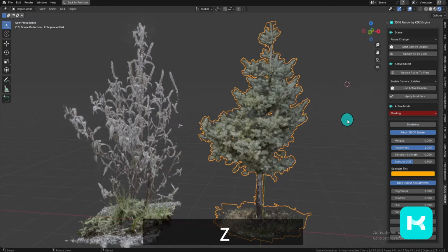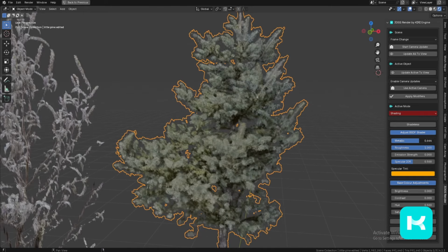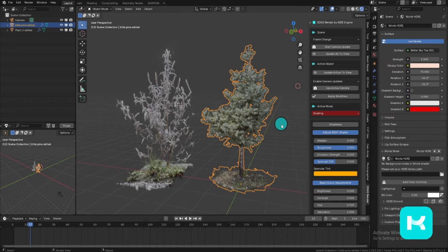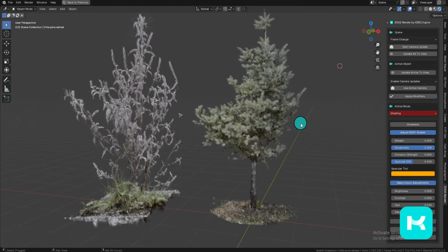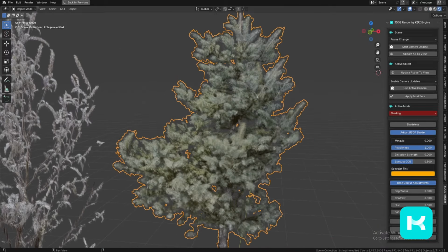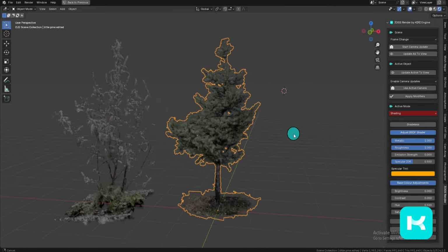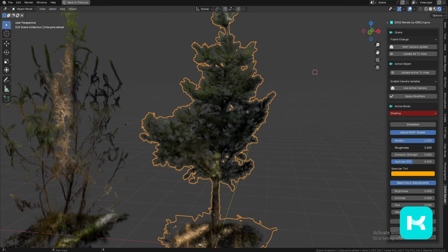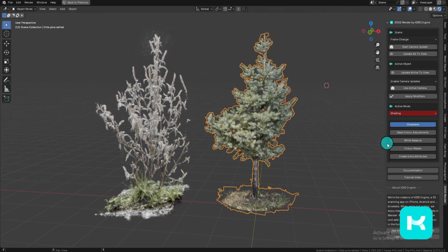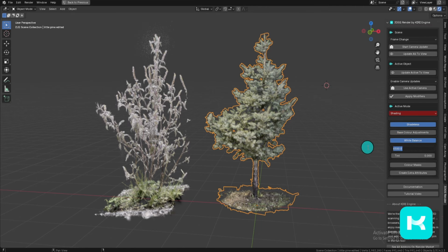If shadeless is disabled, BSDF settings for metallic, roughness, emission strength, and specular are shown. Because the object is composed of single flat faces, adjusting the BSDF shader will not give results comparable to a normal polygon mesh, but it can still be useful to fine-tune the material's look. Toggling base color adjustments shows options for manipulating the material's brightness, contrast, hue, and saturation. If white balance wasn't accurately set during scanning, you can adjust the white balance.